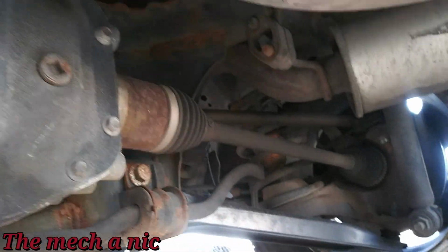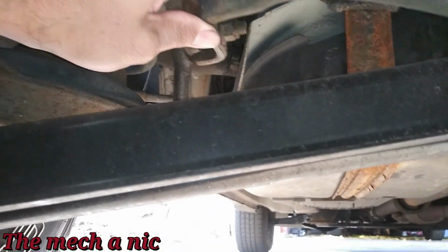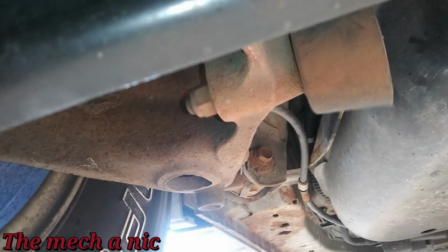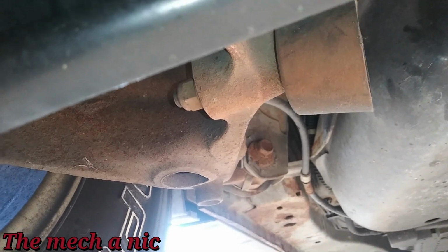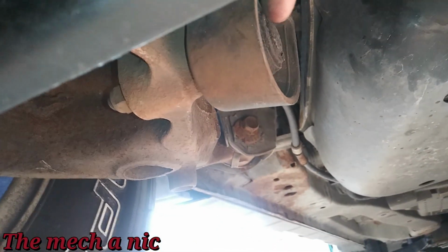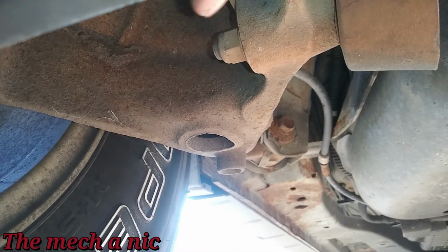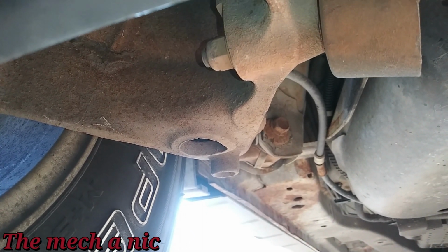Yeah, I guess tow. It's brand new on both sides. So someone was just in here. Did they have to remove the stabilizer links to replace these parts? I don't know. But these parts, there's no reason why they should be that loose. You know, on old worn out parts, the joint gets worn out. It doesn't normally back off like this unless someone was in here messing with this, or someone just forgot to tighten it.